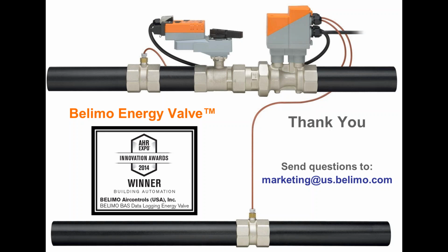Okay. So in general, if you don't connect the DDC to the energy valve, there's no way for it to modulate based on any input. In other words, it only takes a 0 to 10 or 2 to 10 or 4 to 20 input, if you do it that way, and that needs to be generated by something.